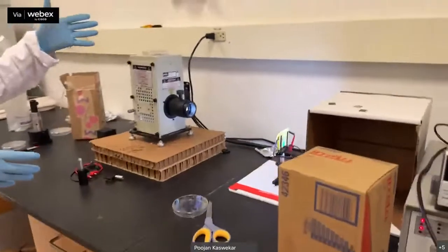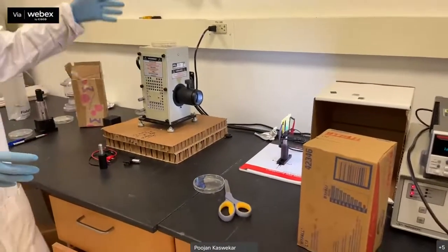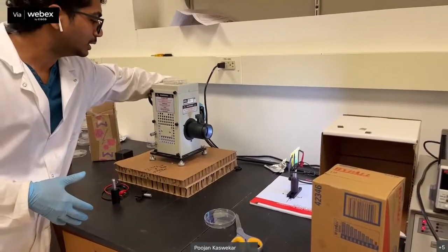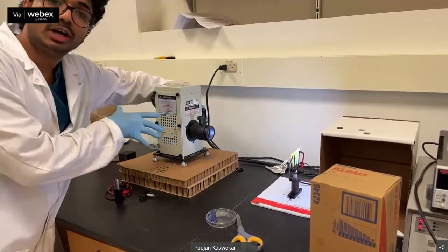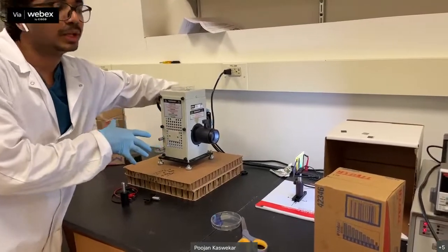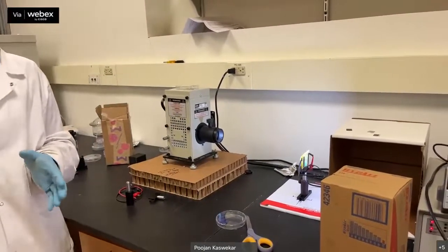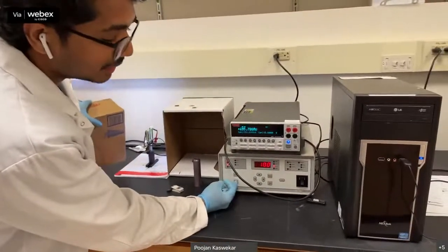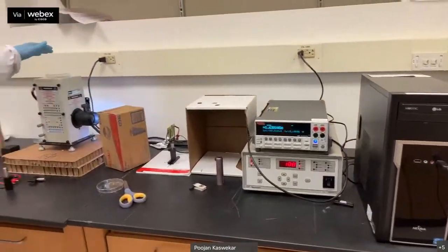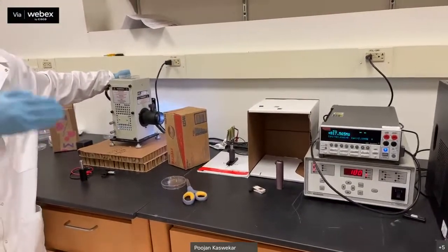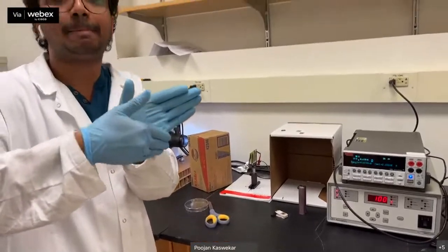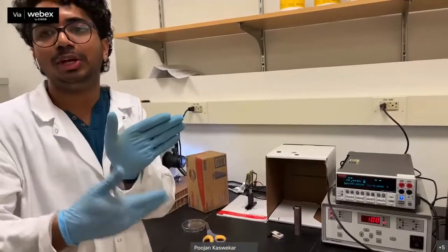So this is the typical distance in xenon arc measurements here. And there is a cooling fan on this side. There will be a cooling fan for this xenon arc lamp because the temperatures are much higher. So you want to turn off your lamp only when it has cooled down. Typically, when you are turning it off, you turn off the lamp here and let the fan keep running, and only then turn off the fan. Otherwise, it will form a black film on top of the lamp, and it won't give you the illumination you wanted.